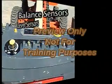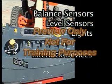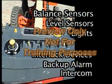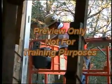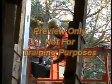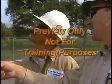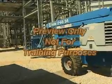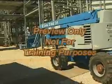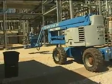Check balance sensors, level sensors controls, lights, interlock devices, backup alarm, and intercom for proper operation. The emergency descent system should be checked by raising the platform a couple of feet and then turning the lift off and using the auxiliary power to lower the lift. It is necessary to always inspect the work site prior to using the lift. The ground on which the lift will be used needs to be solid and as level as possible. Do not use a lift on unstable ground.